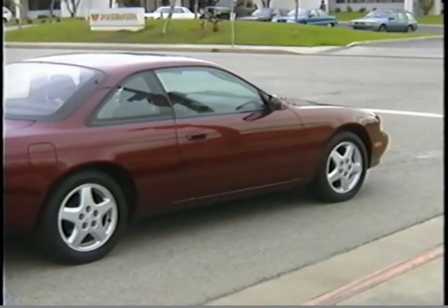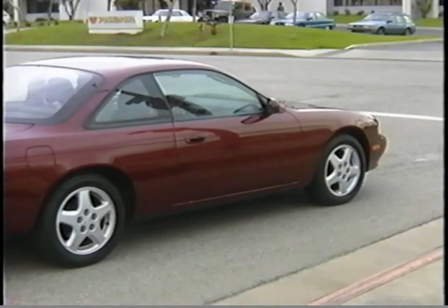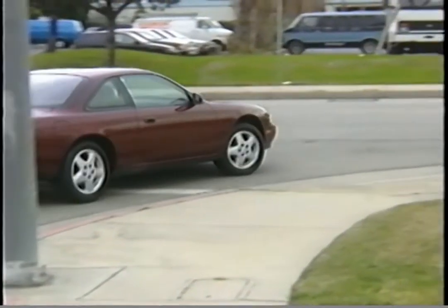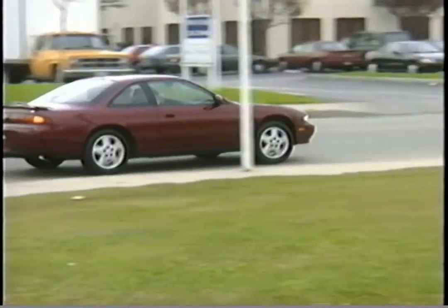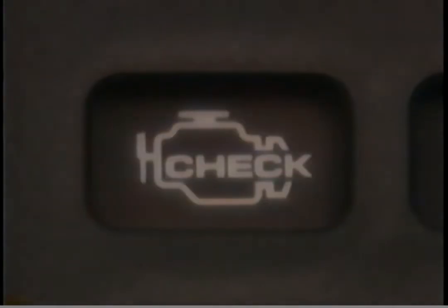If a vehicle with a misfire experiences only a light load, the MIL will illuminate steadily. But if the vehicle is driven under a load that is moderately heavy, the MIL will blink to indicate that this condition is very harmful to the catalytic converter.